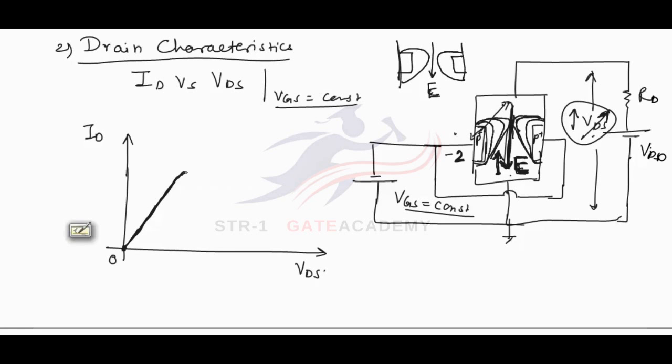So at this point, this voltage is called pinch off voltage Vp. At this point, drain current ID saturates. At this point, both the depletion layers touch each other, and this voltage is called Vp. Remember that this voltage Vp is different from the voltage that was seen earlier.